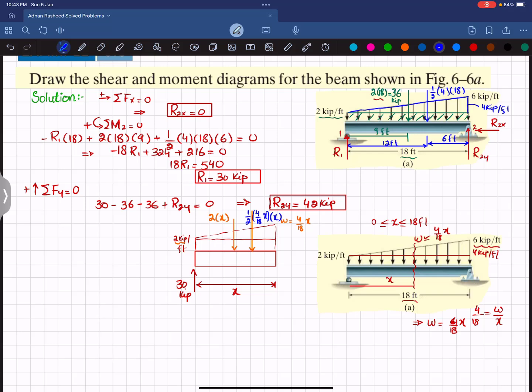So when you cut it, you will be having a shear force V, as well as a reaction moment at the section where you cut it. Okay, this is M. So we'll find this V and M by using equations of equilibrium. So the first equation of equilibrium is that sum of all forces along y direction must be equal to 0 and upward force is taken as positive.